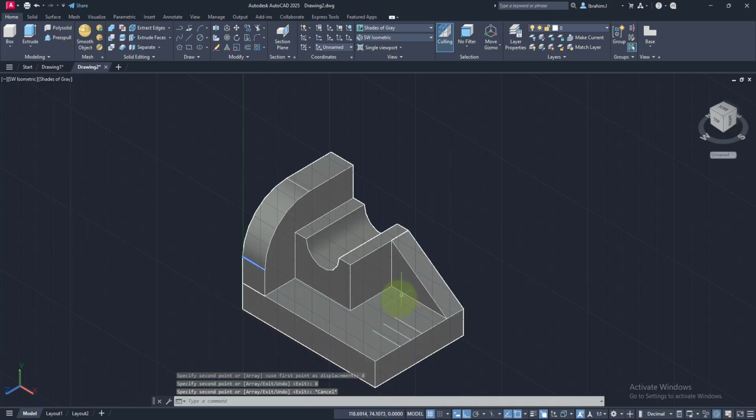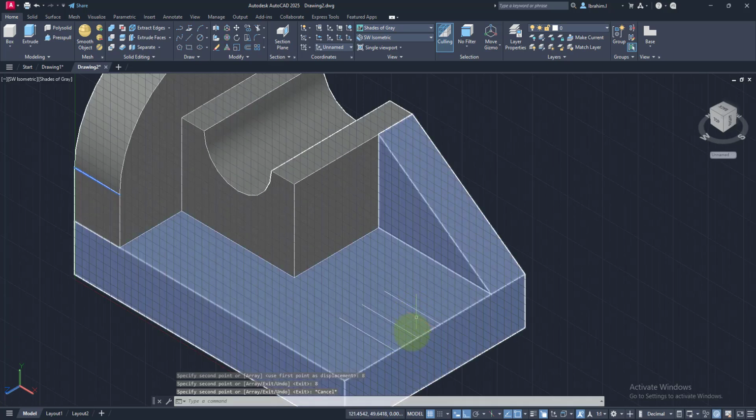Now that I have both shapes created at the distance of 8, you can see that I just used a copy command so that I don't stress myself. Object Snap will make that easy for us. I can go ahead and use offset, but offset can be more complicated, so I don't want to complicate life.